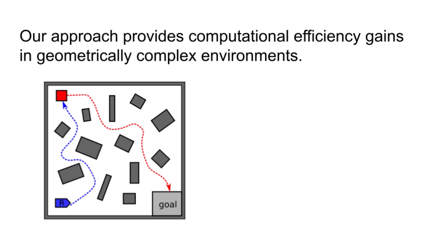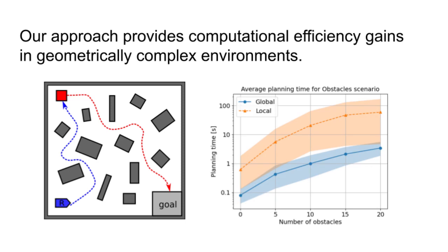For example, here we explore planning in increasingly cluttered environments. As the environment becomes more complex, the local reactive planning approach requires a larger number of samples to successfully plan by checking for collision-free straight-line motions. Our global reactive planning approach allows expressing the plan as only two transitions, first to establish contact with the red box, and second to place it in the goal. While our approach is topologically unaffected by clutter, and can plan with a modest number of samples while guaranteeing correctness, we still see an increase in computation time from polygon calculations.